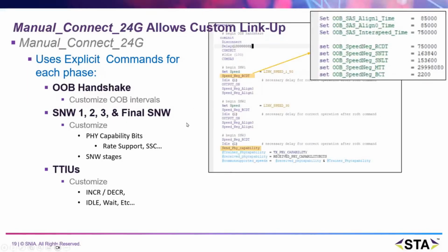The SAS protocol begins with an out-of-band handshake, also known as the OOB handshake, a low-speed signaling process used to establish a physical connection between two PHYs before any high-speed data is exchanged. This sequence includes key primitives like COMINIT, sent by the initiator to signal link initialization, COMWAKE, sent by the target to confirm readiness. The COMSAS primitive identifies the device as SAS capable, as opposed to SATA.